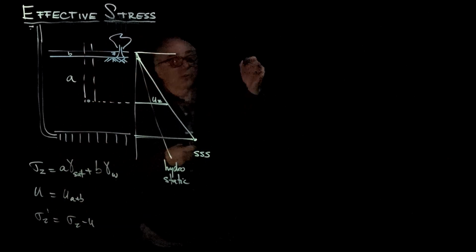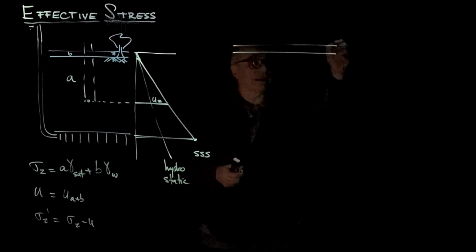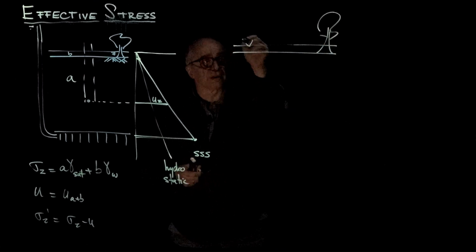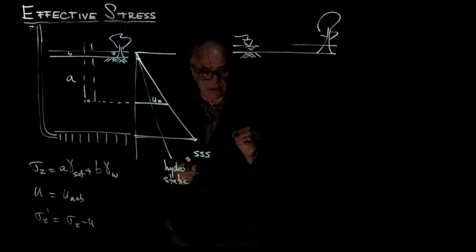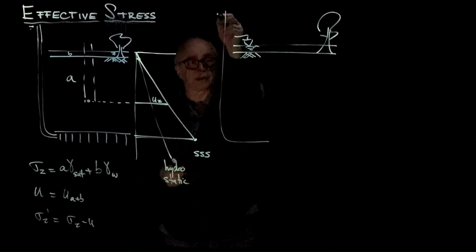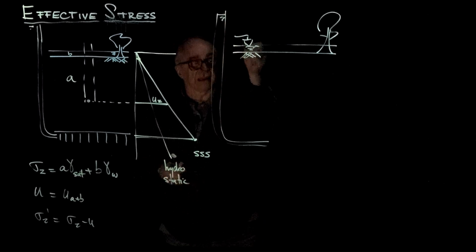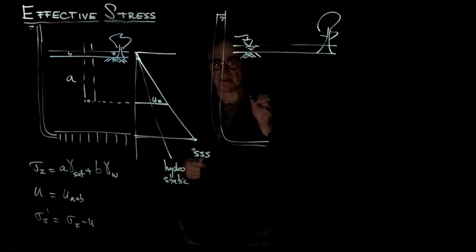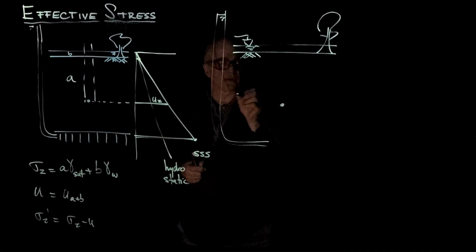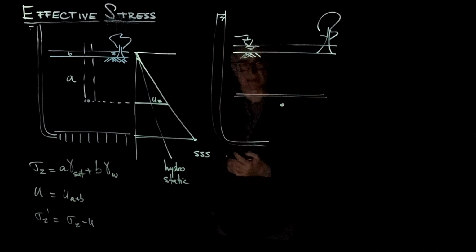The situation could get even more complex or interesting if you do have an Artesian pressure, so the pressure at the bottom really shoots up above the lake elevation or the river elevation, but there is a layer with very low permeability. There is an aquitard.